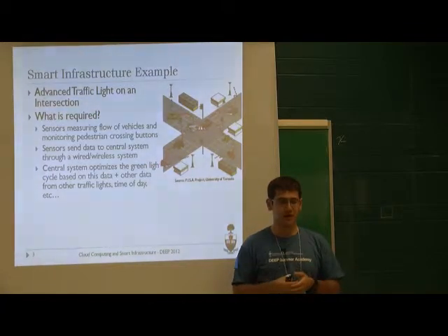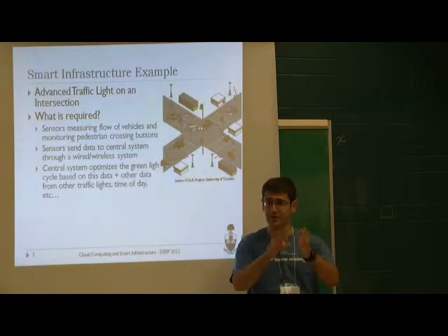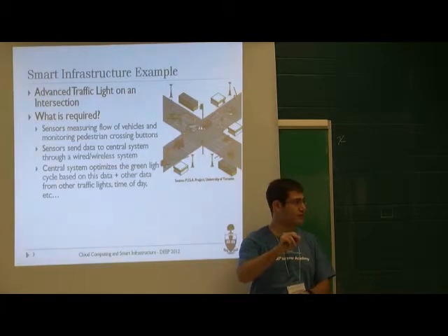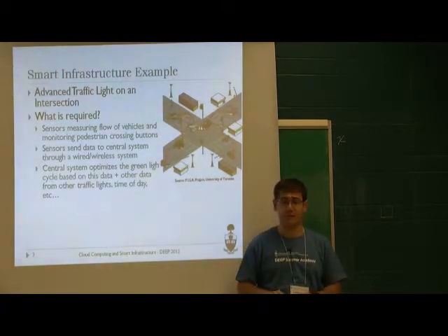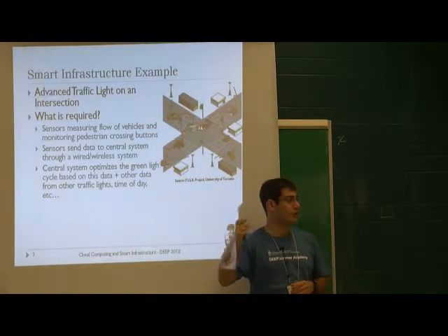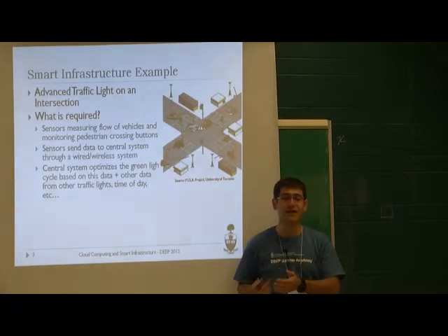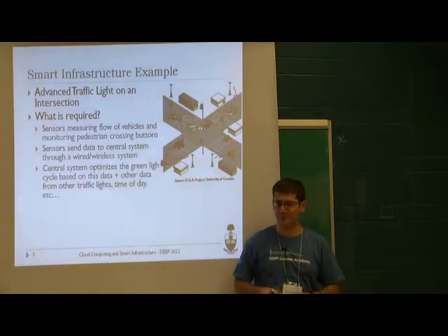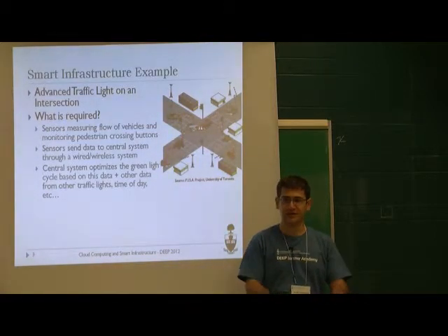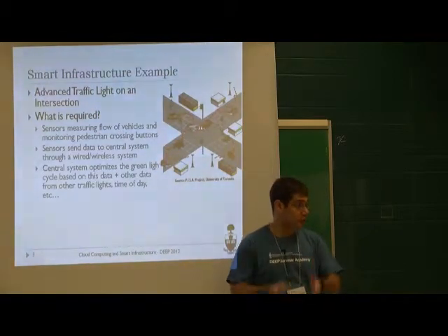So imagine the vehicle's going north. It's really busy, or you have many vehicles going. And just before they arrive at the intersection, you have that sensor. Now, there's someone trying to go west. They keep on pressing. If they press, and during that same time, on the sensor, there's still a vehicle coming, the green light won't change. Why? What's the most important element in the system? It's how busy the vehicles are going north.